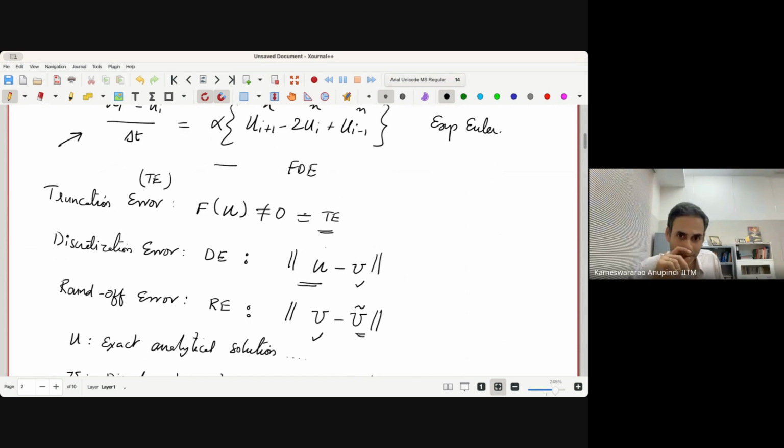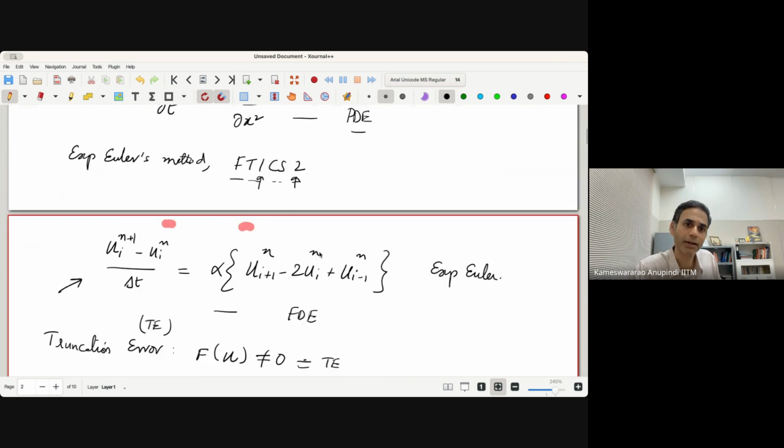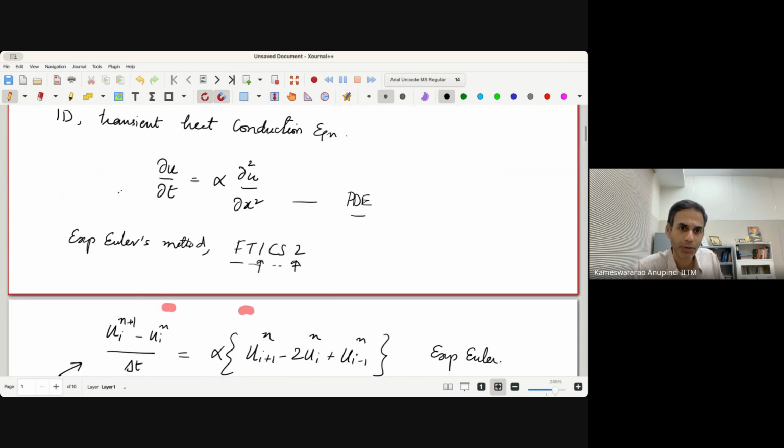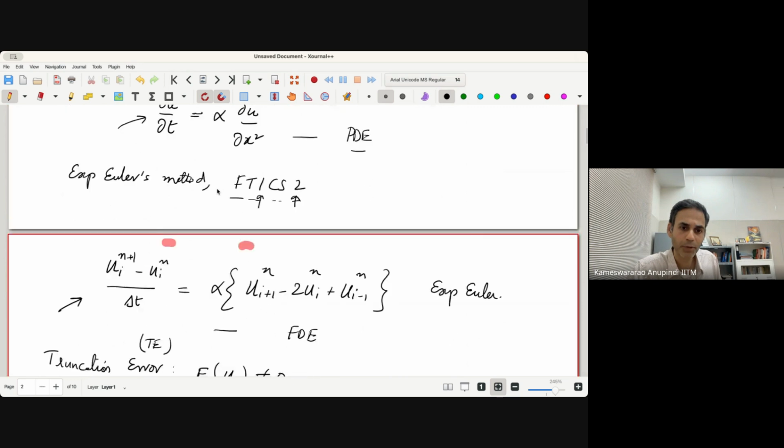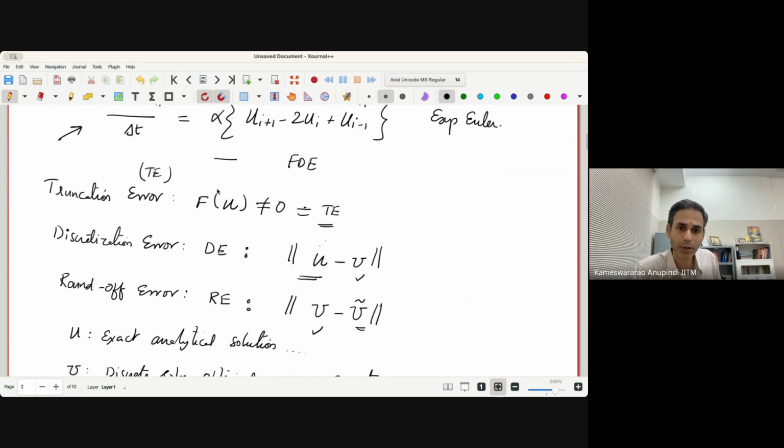No, there is still meaning, because you will be able to calculate this, for example, for the one-dimensional heat equation. You can obtain this analytically for this problem, and for a range of problems. But for all those problems where you won't be able to find the exact analytical solution, you cannot calculate this discretization error as such.